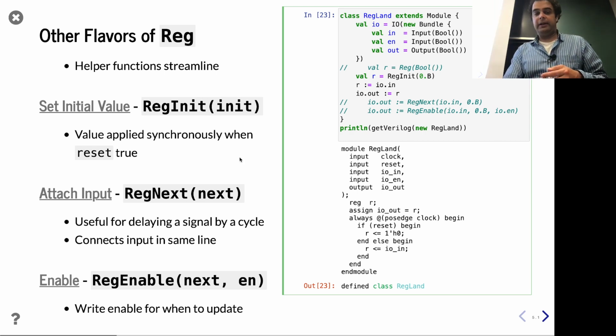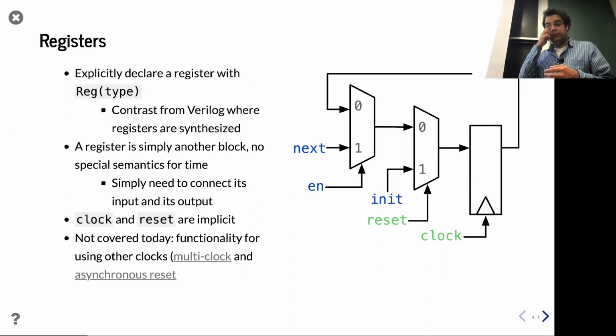Yeah. So to clarify, there's two things you can do, right? When you modify these things, you can make things explicit rather than implicit. So you can say, no, don't use the global implicit reset. Use this logic signal I've manually constructed, which has certain constraints to it. That's one option. In the case of asynchronous reset for registers, there's actually a way to do it.